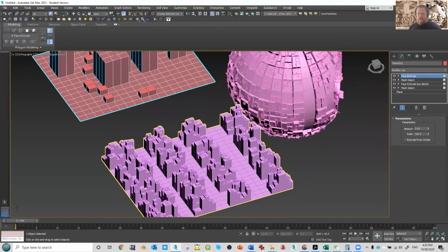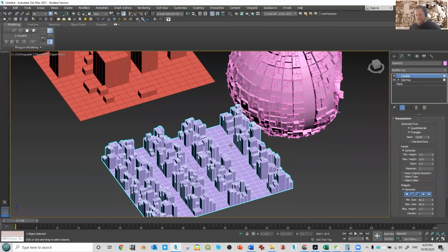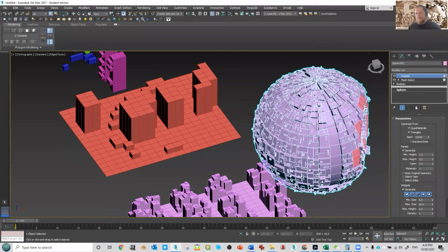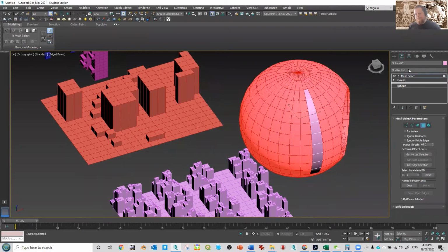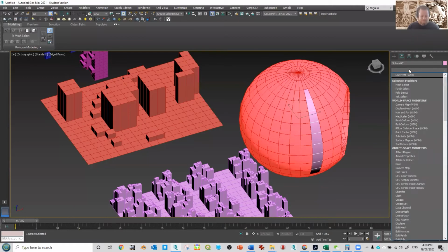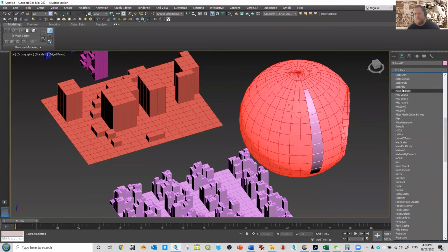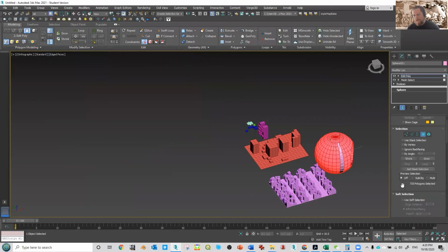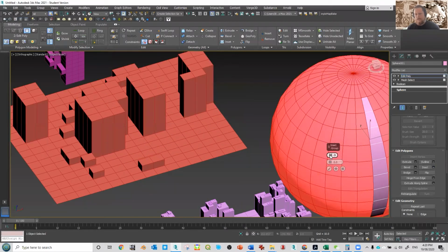That's certainly worth doing when you've got more complex bits of geometry and you're doing some edit polys. Maybe you're not doing a Greeble on that, maybe it's an animated edit poly, and this time you're doing an inset, which is another useful one.